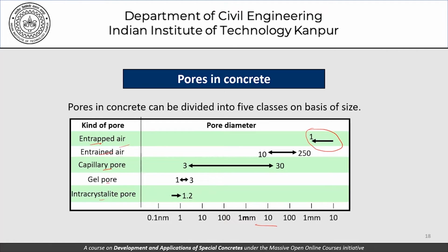So this water is easiest to move out. This water is impossible to move out under normal conditions. This is possibly somewhere in between. So once we talk of how much water can be moved out, we have to go back to some kind of a diagram like this. Remember that water sitting in larger spaces is easier to move out. Water sitting in smaller spaces is more difficult to move out. Keep that in mind when we study other characteristics of concrete as well.